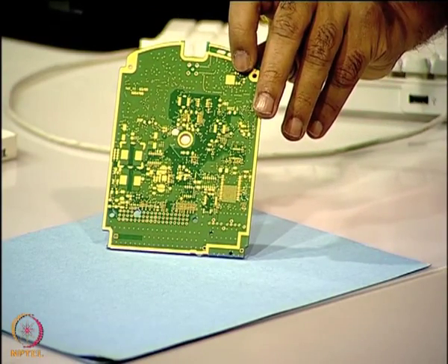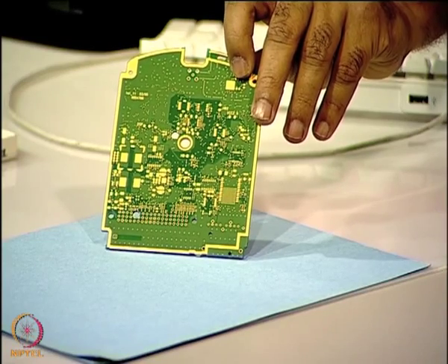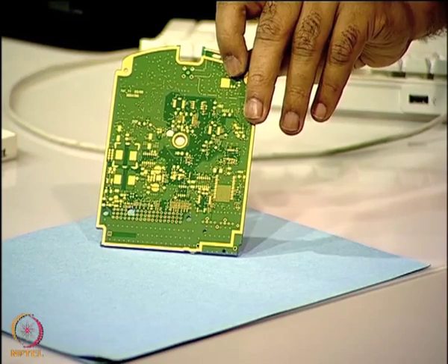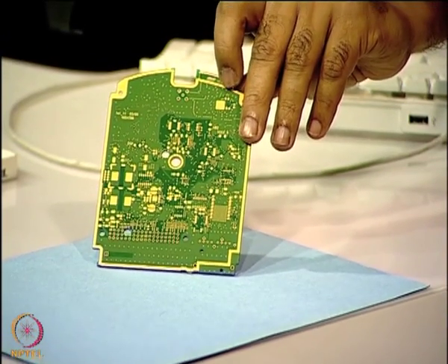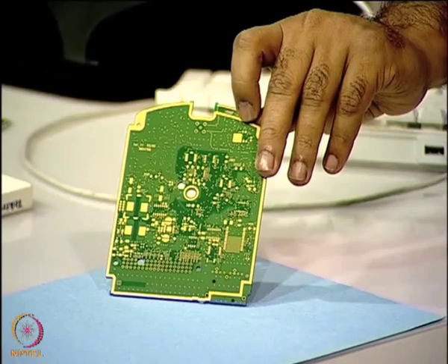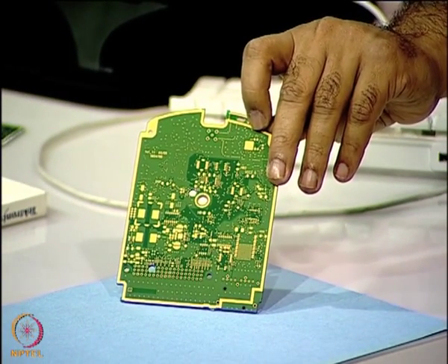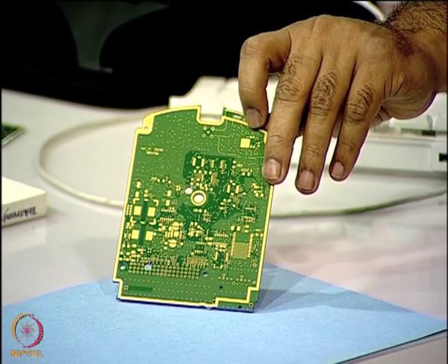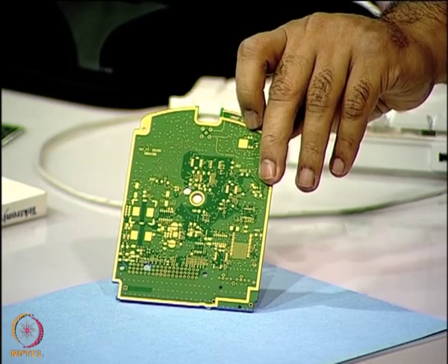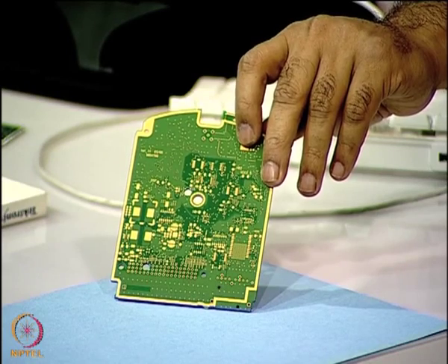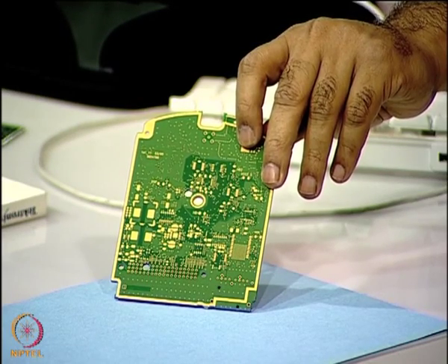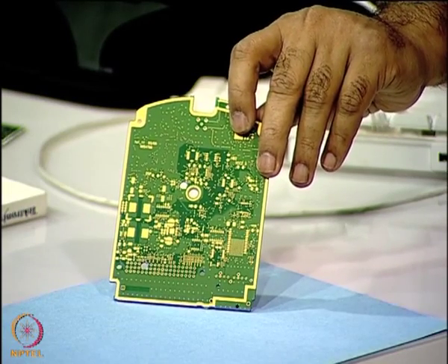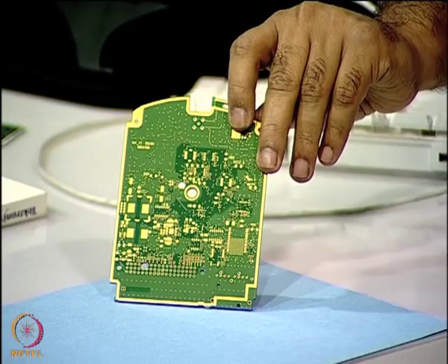This is a gold plated printed wiring board, and in fact, if you look at it very closely, this has mechanically drilled through holes of the order of 0.15 mm, that is 150 microns, and these through holes have been made electrically conductive. That means they have been plated through hole in these PCBs and they are highly reliable. So, these are used for specific applications. This is a high density